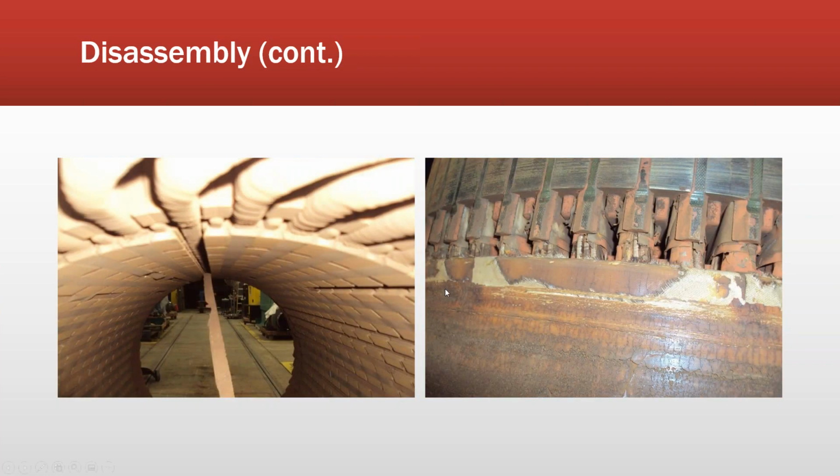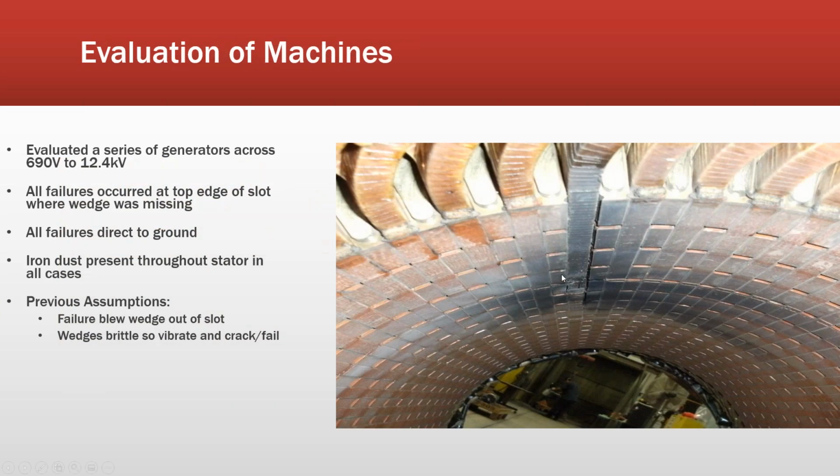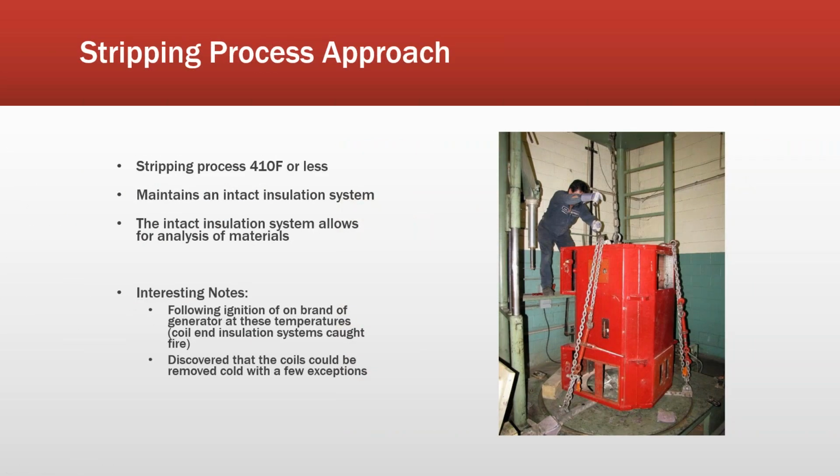And of course, when that occurs, that stuff eats away at everything, but it does something else pretty cool, and that is something that Nikola Tesla used to demonstrate in the past called magnetic termites. So all that little ferrous material gets on the winding, starts spinning and working its way into the insulation system until I get a track and it blows to ground. So we found that across a number of different generators.